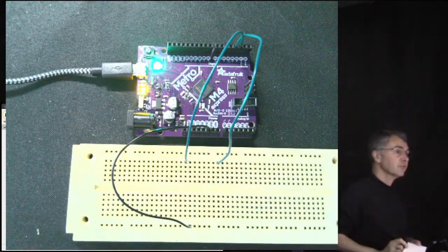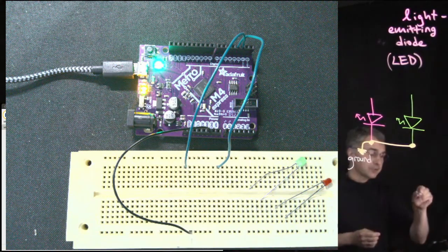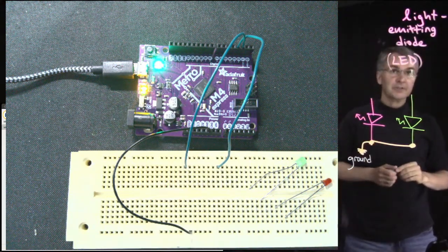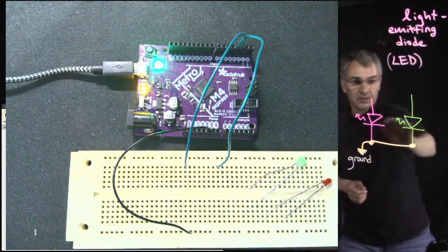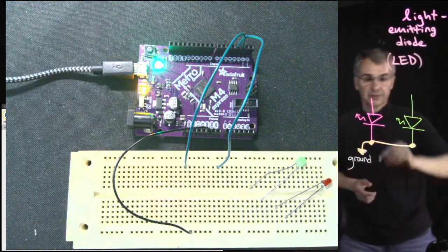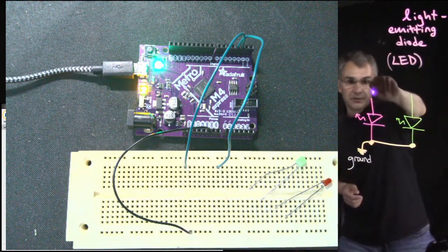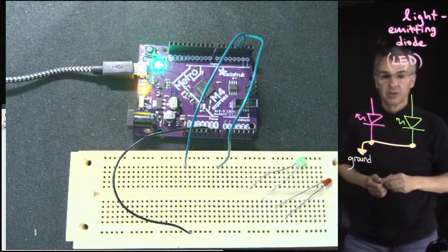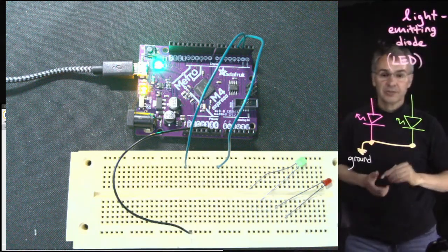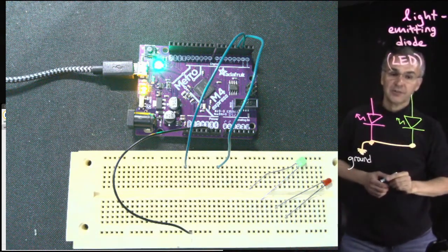Now, in my handy box of parts, I'm going to find a red LED and a green LED. An LED is an example of a diode. A diode is a device through which current can flow only in one direction, and there's usually a little triangle and a straight line on a schematic symbol for a diode. So the little triangle gives you the hint that current will flow down but not up. So you can make current flow through this thing in what is drawn here as the downward direction but not the upward direction. These are light-emitting diodes, so you draw a little photon coming out of the diode symbol, and that reminds you that it is light-emitting.